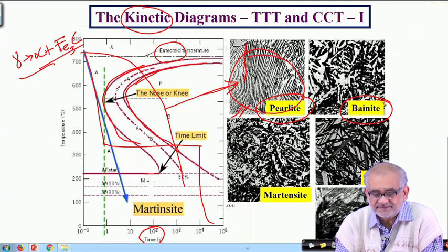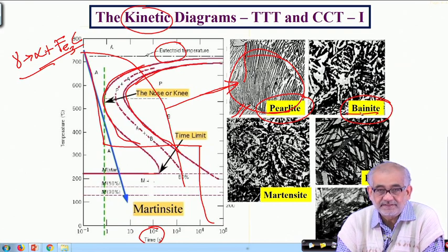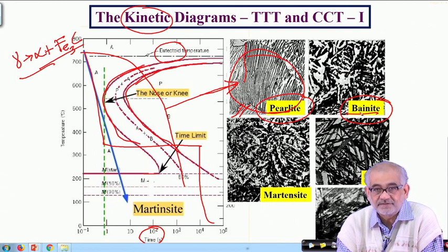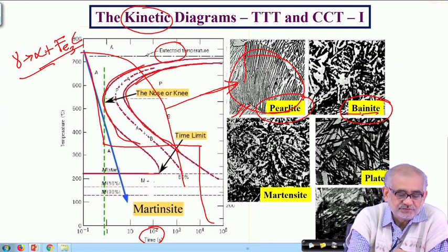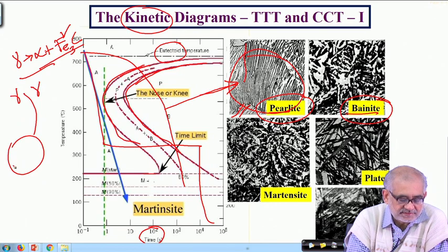The interesting fact here is that we are talking about two aggregates, pearlite and bainite, which are nothing but phase aggregates. The difference lies primarily in terms of the appearance or the microstructure, but also in the mechanism. In case of pearlite, usually cementite nucleates first. So essentially, if you are talking about two grains, so if this is the prior austenitic microstructure, all grains are gamma or austenite. So on this boundary, you would first happen to see